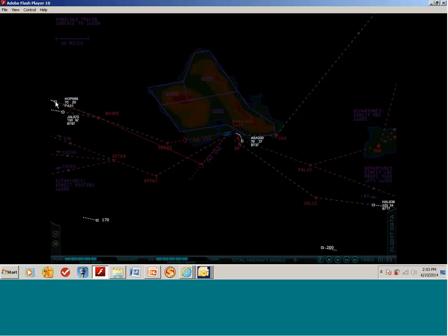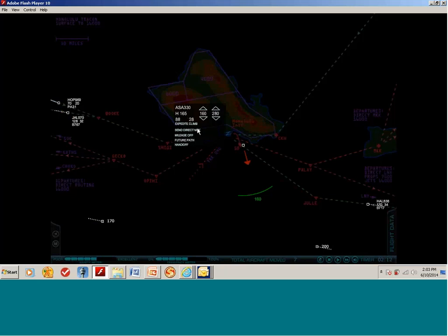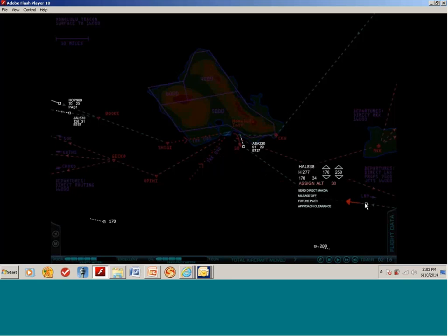This guy here is landing on the other runway, so I want to get him down here. Now to send him to 2. 969, maintain 2,000, right heading 150. I'll turn this guy direct to Molokai now. And this person here, I'll give him a heading about 280 and go to 4. Because I also have large and small airplanes coming in this way. The Navajos I'll take down to 2, but the Dash 8s I'll take down to 3, and the Jets I'll take down to 4.